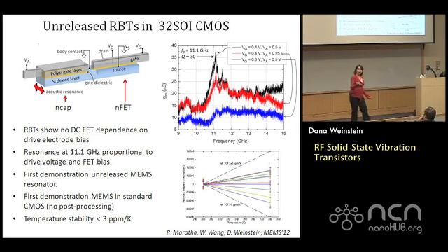So typically, silicon has a temperature coefficient of frequency, TCF, which is roughly minus 30 ppm per Kelvin. In order to compensate this temperature coefficient of frequency, people do a couple different things. Either you can correct for it with, say, ovenized systems, depending on how much you want to pay for your oscillator and how much you care. But there are also passive ways to compensate.